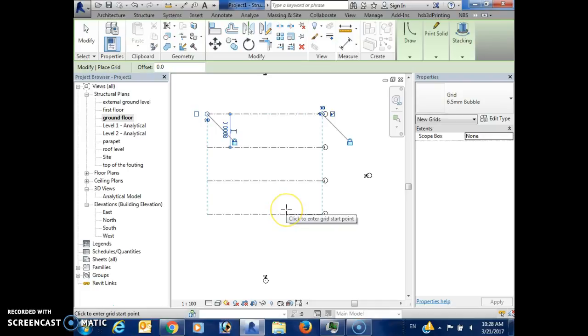When we are working on the structure, the first element that we draw is the grid, if we know it. If we don't know it, we'll create our structure and then the grid. But if you have a defined grid where all your elements are gonna be, the first thing that you have to create is the grid. It's the easiest and the best way.